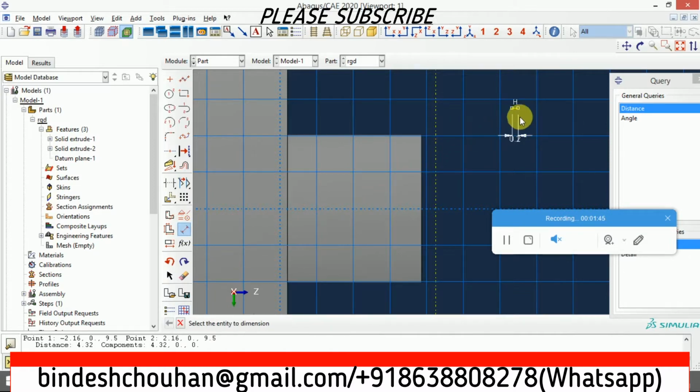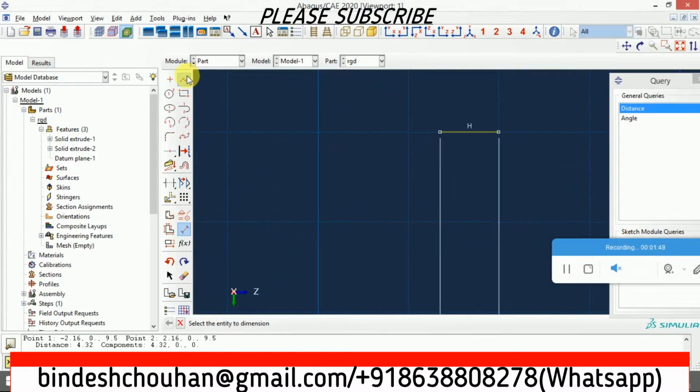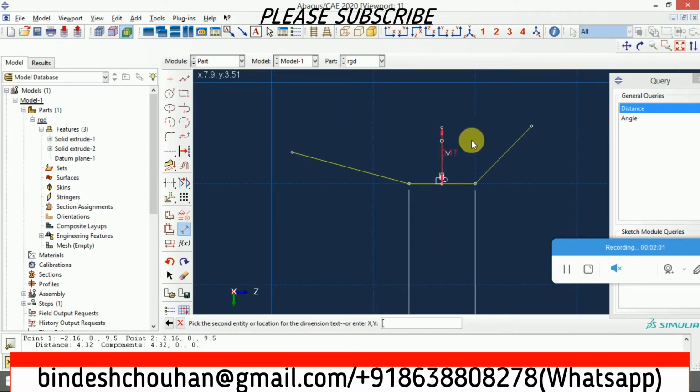Now what we'll do is draw a vertical line and two inclined lines. Just draw two random inclined lines, and now we'll try to make the angle 30 degrees. Select the first vertical line, because we don't want the vertical line to move.